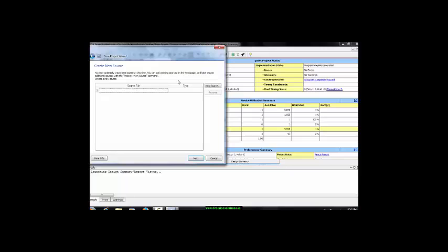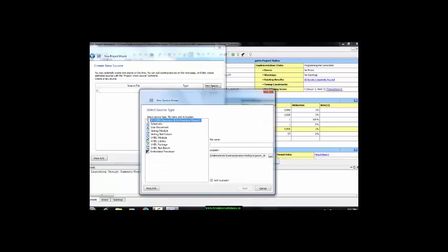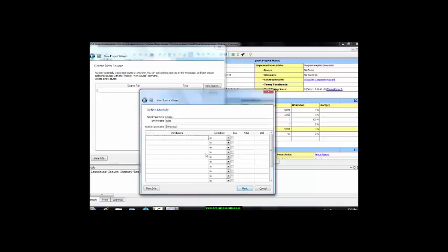Okay, we have to create a new source. Click new source here. Now since we are going to design our circuit in the VHDL language, we have to select the VHDL module for it. Let the name for that file be gate. We have to add this file to the project. Now it will have the extension of .vhd. We'll see it later on.